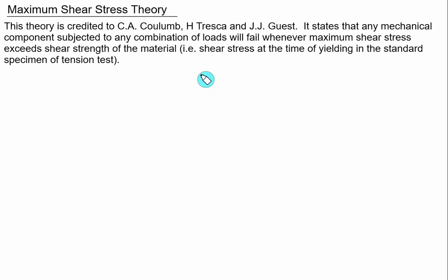And this theory says that any mechanical component subject to any combination of loads will fail whenever the maximum shear stress. So maximum shear stress means absolute. So you have to convert the two-dimensional problem into a three-dimensional problem, and one of the stresses you have to consider equal to 0 when we convert from two-dimensional to three-dimensional,